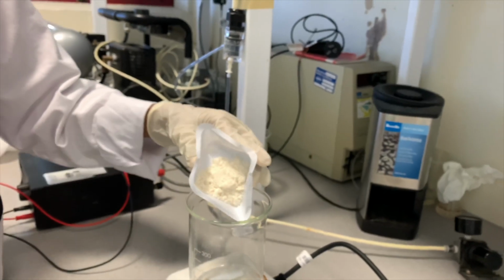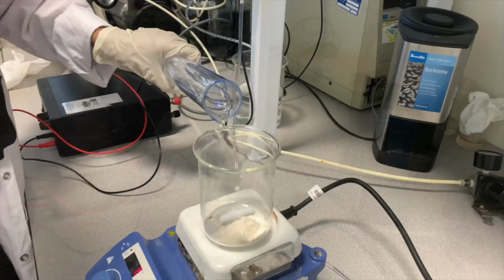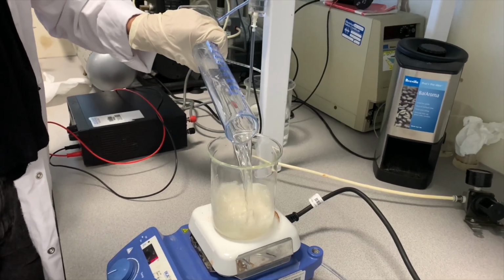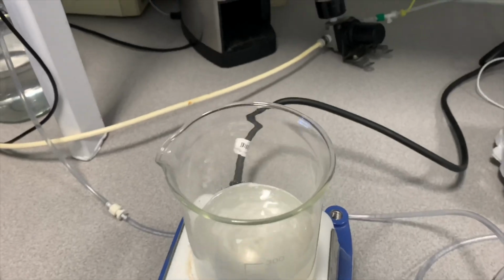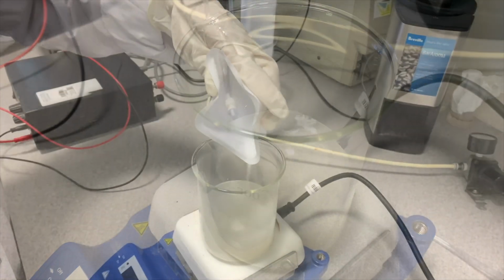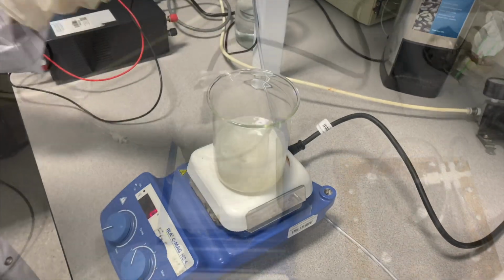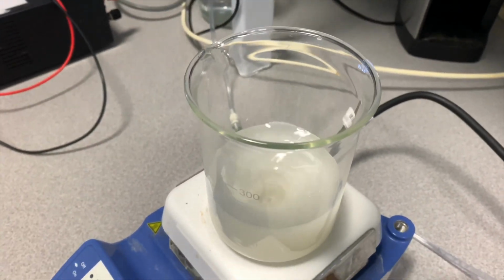Start by preparing the model whey solution containing 1500 ppm of NaCl. We mix 3.75 grams of whey protein isolate with 150 ml of deionized water in a beaker using a magnetic stirrer at 1.5 rpm and at room temperature until it reaches equilibrium. Then we add 0.23 grams of NaCl to the whey solution, and then the solution is mixed.